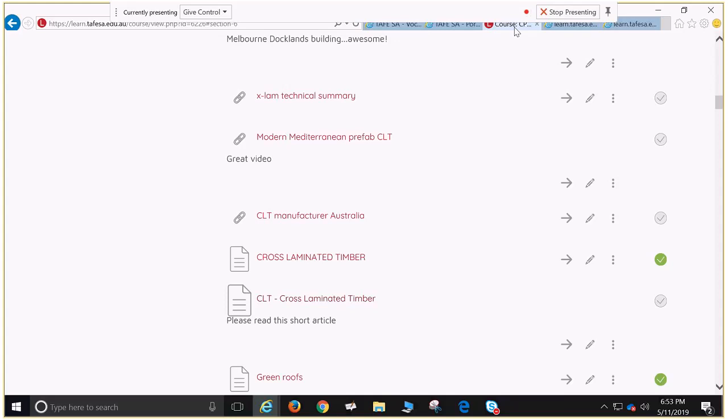Whereas timber that does lose a lot of its moisture and weight during seasoning will have a lot more air in it, so it has higher resistance to the passage of heat and cool, but lower retention of heat and cool. But you mentioned steel, and steel is very conductive. Steel will conduct heat very well, but it still does have quite a high thermal mass. There is a lot of density to that material.